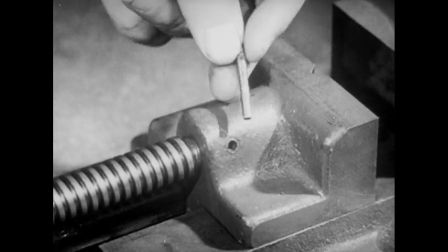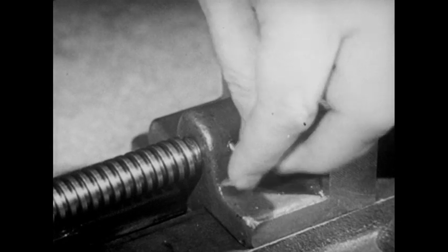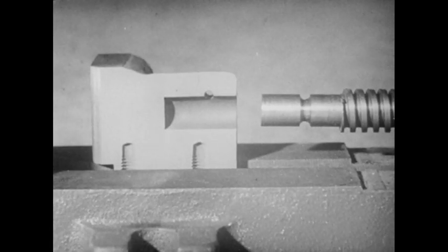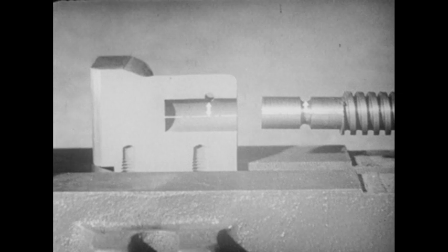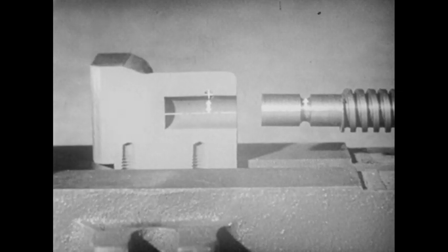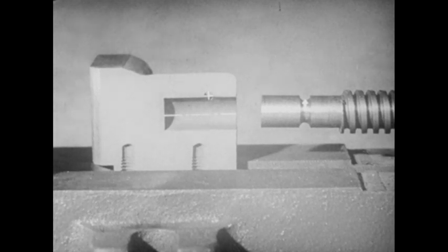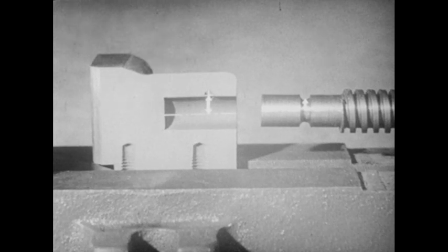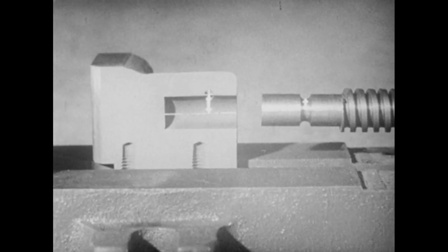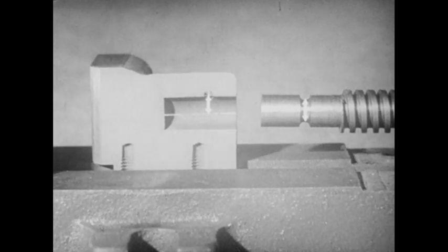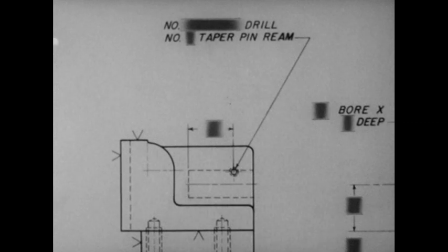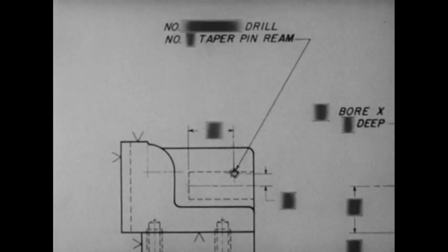When the shaft and the pin are in place, the pin must clear the bottom of the groove in the shaft. This means that the distance from the bottom of the groove to the center line of the shaft and the distance from the taper pin hole to the center line of the shaft hole must be correlated. Again, however, the shop must locate to the center line of the taper pin hole. Therefore, give the distance from the center line of the shaft hole to the center line of the taper pin hole on the movable jaw. The directly correlated dimension on the shaft would be impractical to measure. Therefore, use the diameter of the neck as a correlating dimension instead. Show the distance from the center line of the pin hole to the center line of the shaft hole on the side view.